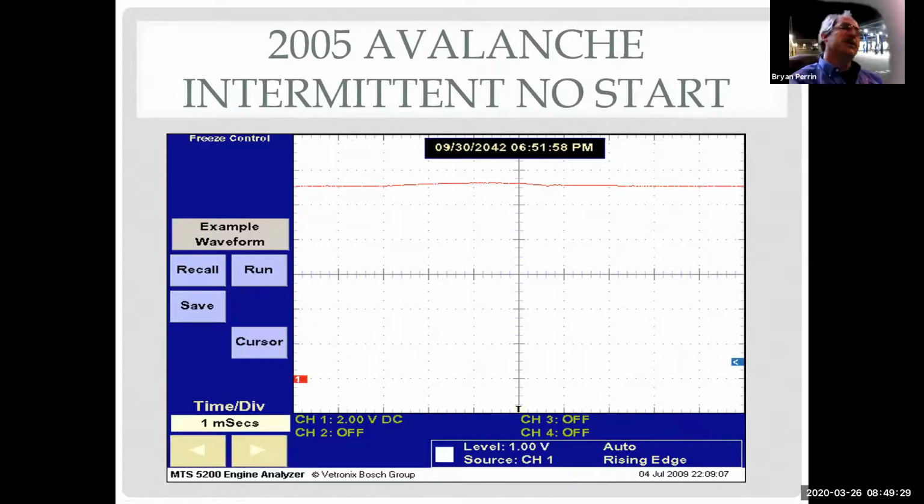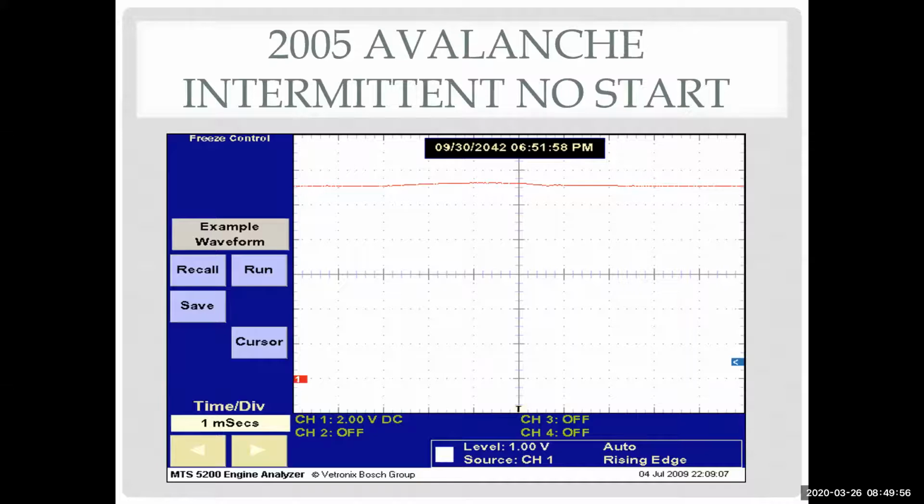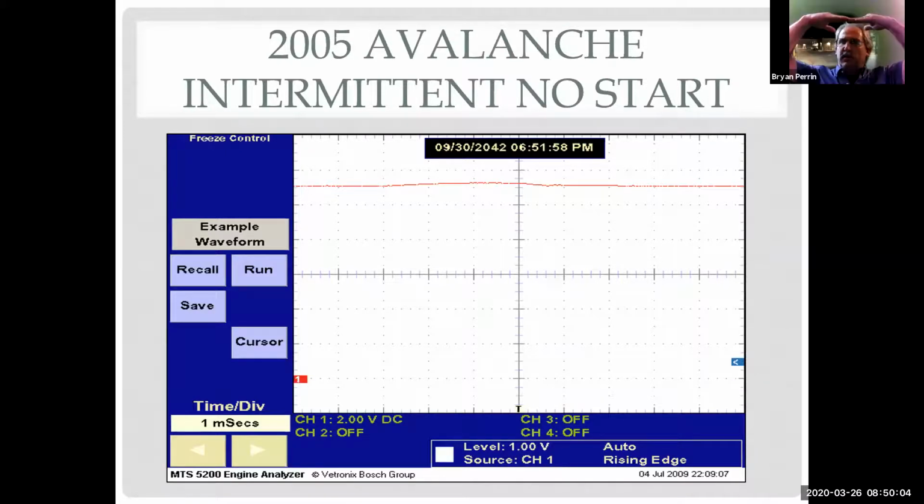Okay, so this is where it's important to know how things work. Because Mario, earlier you mentioned 5 volts, okay? So some systems work 0 to 5 volts, and we know that's not always 5 or always 0 necessarily. This system works 0 to 7 volts. So at rest, I have 0 volts. When someone wants to talk, it goes up to 7 volts. When they're done talking, it goes down to 0 volts. So it's 0 to 7. Well, if I'm moving something 0 to 7 volts, can we see that if I have 11 volts on the system the whole time?